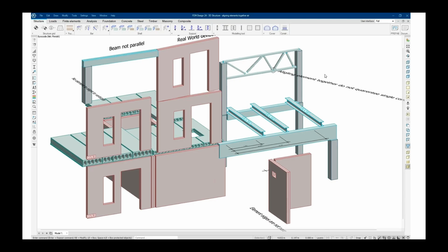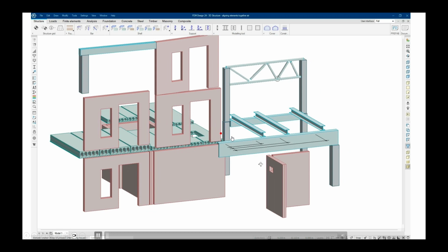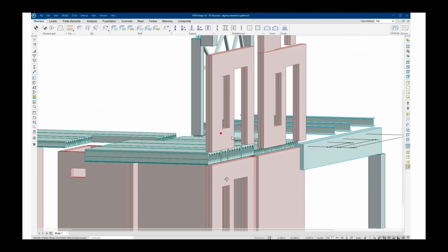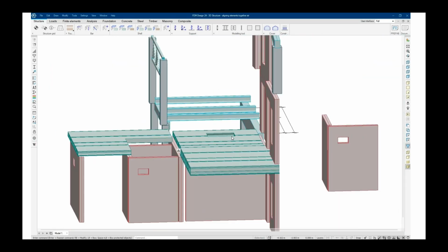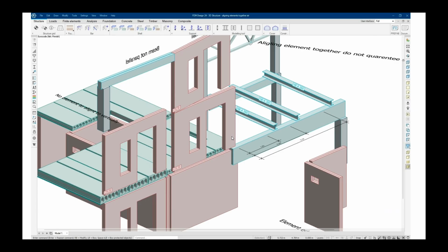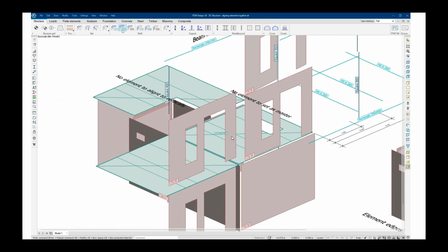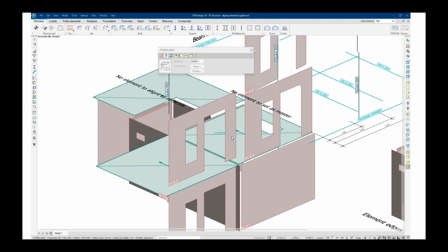So now we do the corrections of this small example model, without any master objects. You can see we have imported the IFC inside the software. There are a lot of gaps. The physical model is okay, and these represent the right locations of the physical objects. But if you look at the analytical model, nothing is connected together. I always recommend that if you have these hollow cores, or what we call profile plates, you turn off the detailed model before you start fixing the model.